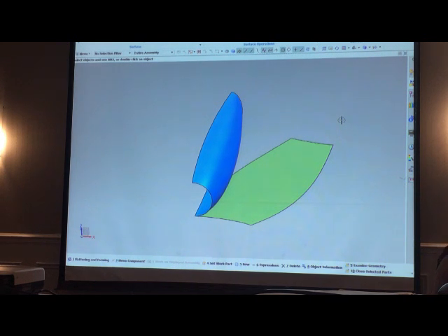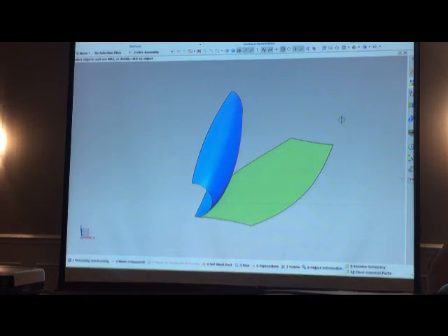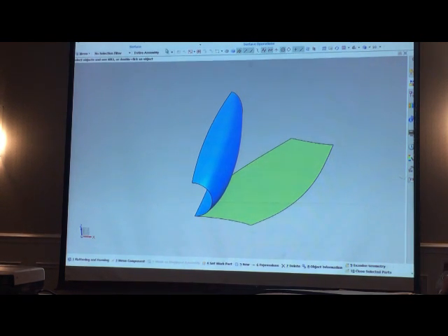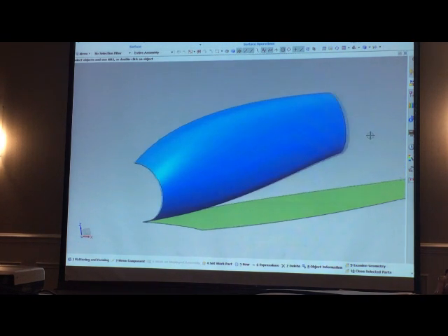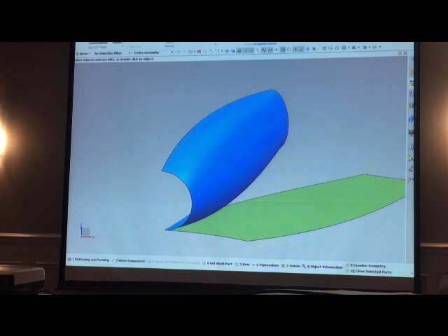And in fact, for thin parts, or just faces, where you're just interested in the face of an object, this works pretty good. In fact, in this particular case, this is what I'm going to do. Now, I want to put an isocline down here along the edge of this. So I'm going to go back to curves, and I'm going to go up here to isocline.